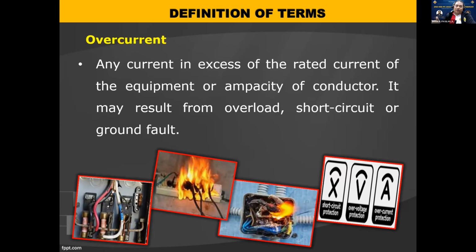So again, overload is just a slight overcurrent, in terms of just a few percent, about 10 to 20% from the rated current. But short circuit is usually 3 to 6 times larger than the rated current. So it is a much bigger difference from overload to short circuit or ground fault, no. So if it is almost a multiple of the rated current, it is either a short circuit or ground fault, no? It depends on the impedance of the system and the available fault duty.